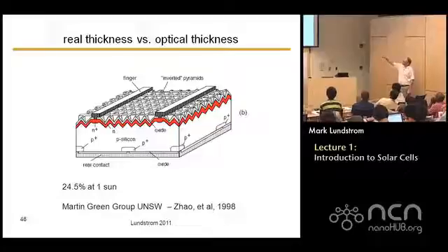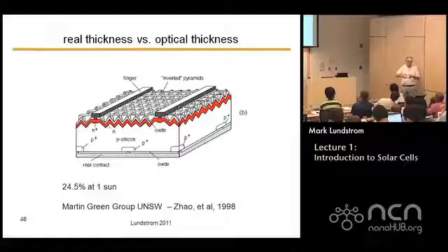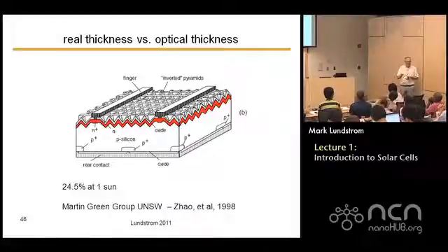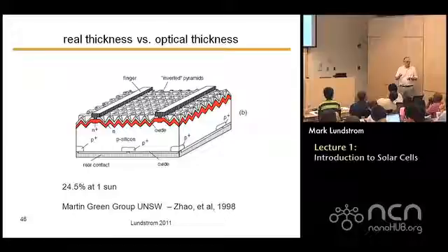There's also another variety of solar cell that also gets near record efficiencies, where the end layer is a small thing like that. They call them point contact cells. So there's a big piece of silicon, it might be either N-type or P-type, but the N region and the P-type contact are very small. So they're trying to minimize the size of the P-N junction, so it's mostly absorbing material.